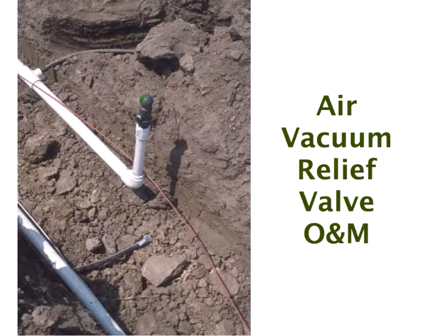Air vacuum relief valves: this will screw off, and it must be screwed off, and again, the more frequently the better. Check that the ball is clean and that the basin is clean for the ball to move up and down. This is a Schrader valve, where you can put on a pressure gauge and measure the pressure in the manifold, either the flush or the supply manifold. They both look the same.